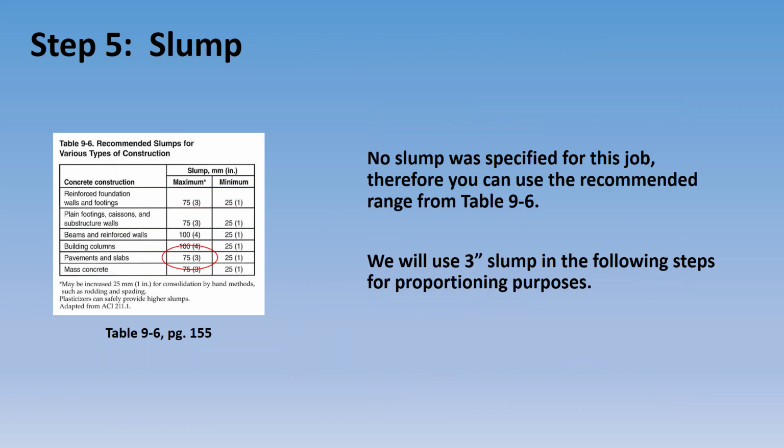Step 5 is just to look at your slump specifications. We don't have any slumps specified for this job. Therefore, we'll use the recommended range from table 9-6. 9-6 is on page 155.